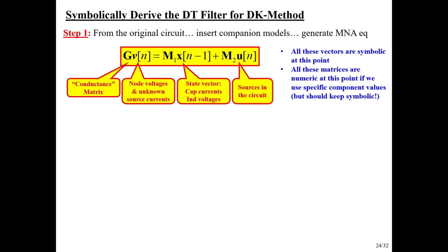And in the code, they should still be symbolic, just drawing from definitions that a user might give for those symbols. That way, a user can adjust the resistor or the capacitance value, or the inductance value, or change the transformer mutual inductance, and so forth. I strongly encourage you to avoid putting numbers in until the last possible minute.